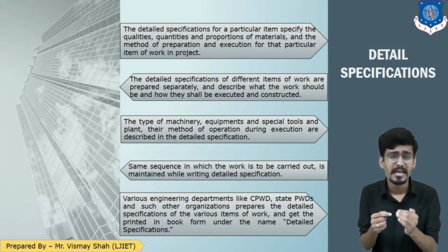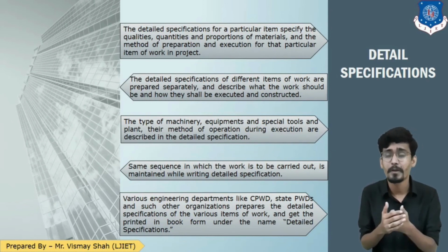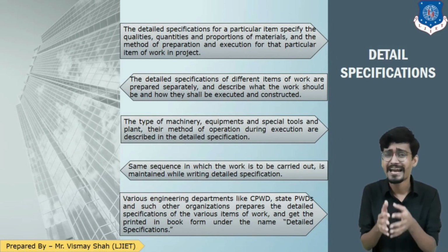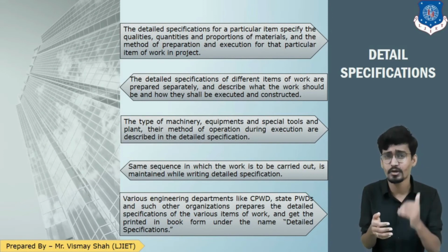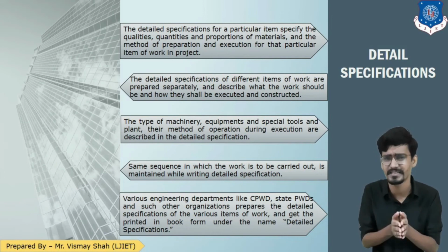For an example, if the excavation is going to be first, then the next is PCC, and then the next is foundation, so I should prepare the detailed specification for the excavation first, then PCC second, and the foundation work third. I cannot provide the plaster specification on page number 1 and excavation specification on page number 36.